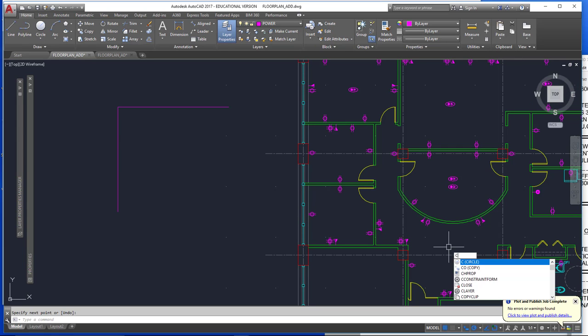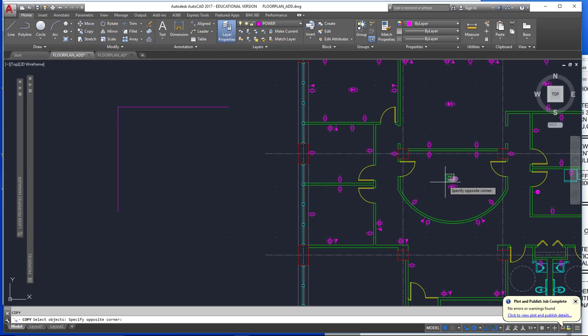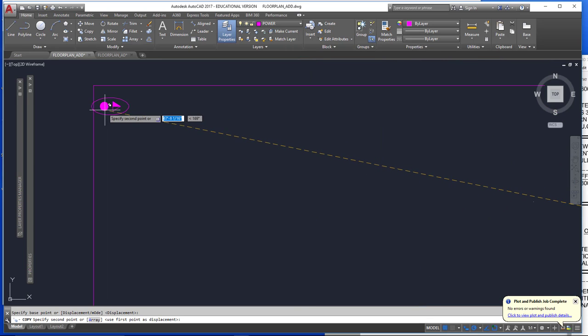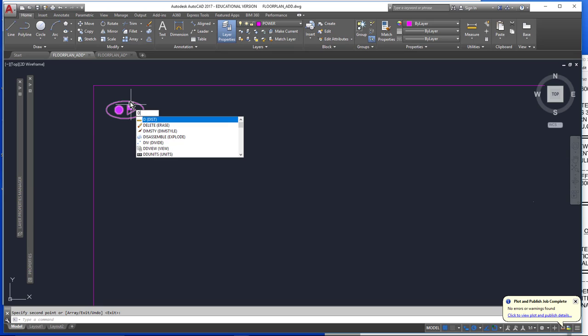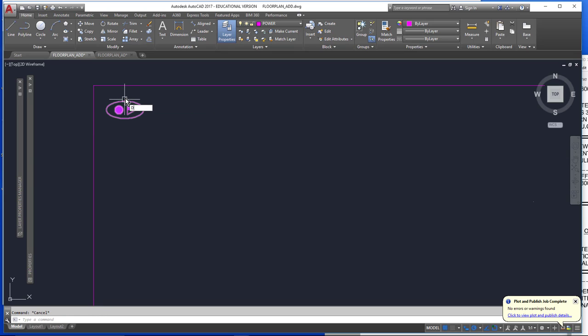One will be whether or not this first part will fit a symbol. This is the largest power symbol that we have. So I'm looking at this and saying, let's see if this looks like it's comfortably located between the two. If I click between here and here, oh look, that's 1'6". So that means maybe the width of this whole thing should be 3 feet. So I'm going to copy this line and go over 3 feet.